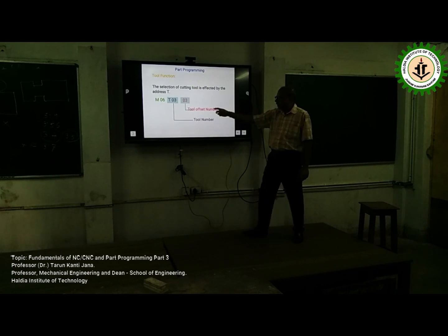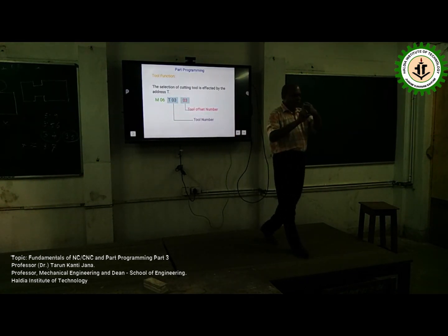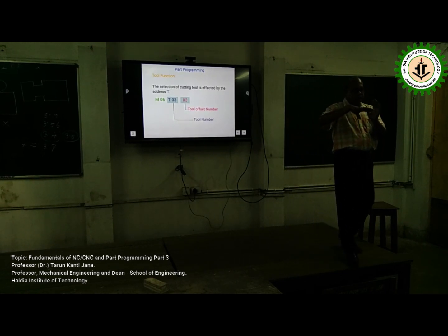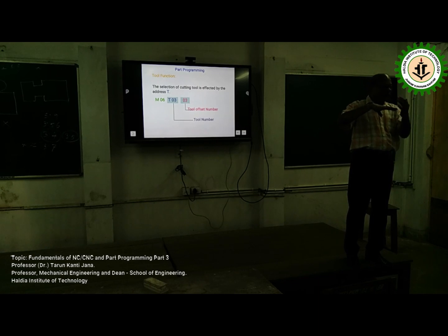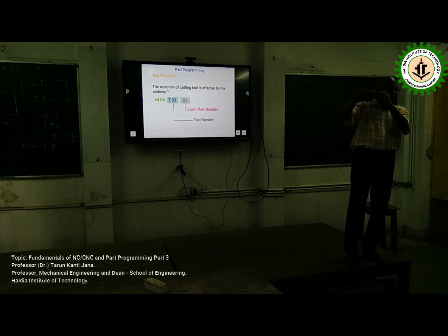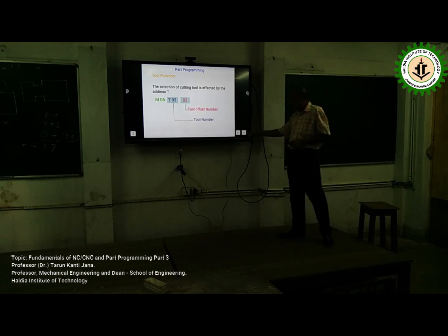Similarly, for tool change, M06 is the tool change command. T03 is the tool number. The system will not be able to identify the purpose of the different fingers, but you can simply identify them as 1, 2, 3, 4, 5. So if you are interested to bring this third tool, you have to specify each tool. That is the indication.